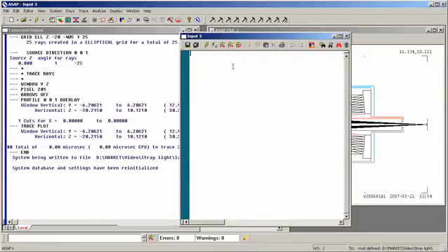So we'll begin here. The very first command I'm going to enter is system from CAS. Recall that CAS was the name of my binary file. It's the file that contains my system geometry and the optical properties. By saying system from CAS, I'm reading that geometry into ASAP's memory so that I can work with it.